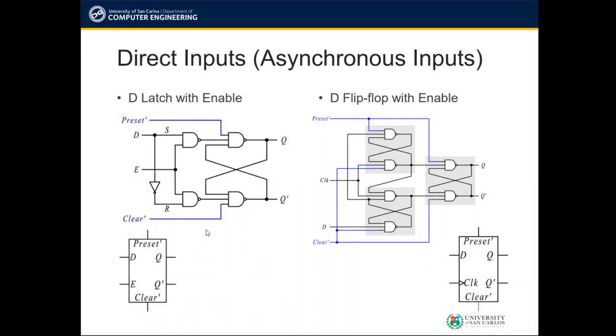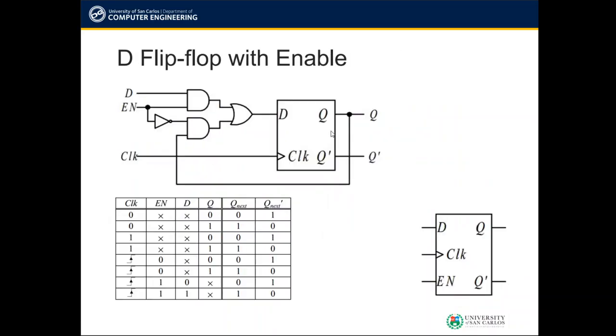So aside from the D flip-flop with enable, we have here the asynchronous inputs. What we mean by asynchronous is that it doesn't look for a timing or a clock for it to proceed or to be activated.